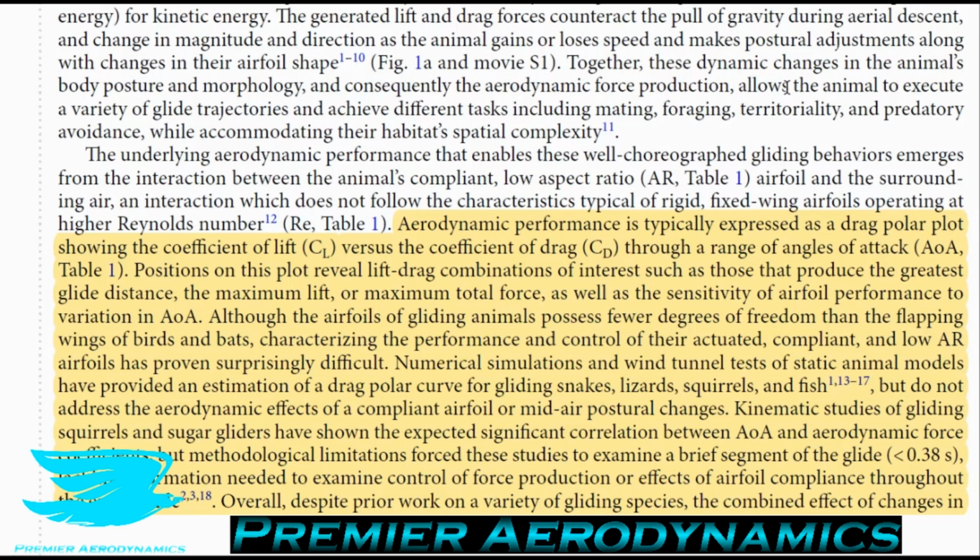If you think about how the wing looks, because they are very stubby, they have very big wingtip vortices. And this results in greater, obviously, induced drag. But what this also does is it reduces the effective angle of attack. This is a concept that isn't often discussed, and when you look into research and books, they don't really discuss it too much. But when you look at the geometry of an aircraft, an airplane, let's say, and the geometry says that it's at a 3-degree angle of attack.